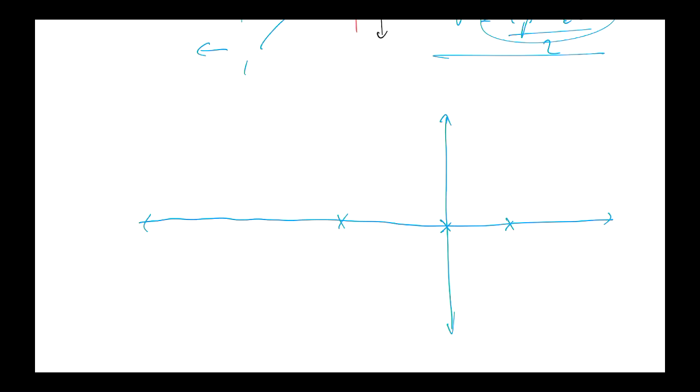So that we could get 0 steady state error for step changes in the reference, say, or disturbance at the output. And then we put a 0 in, all right? And then we put another 0 in and a pole, okay?